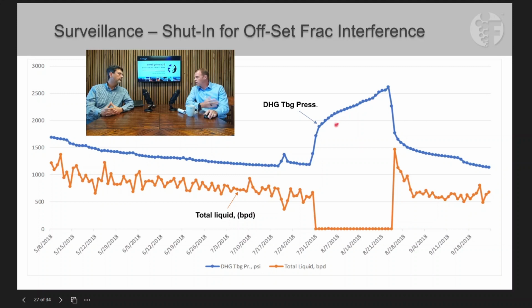Then once we open the well back up or start up the artificial lift system, that drawdown trends back to maybe where it was previously. So we get to see the bottom hole pressure change when we go from a flowing state to a static or shut-in state.